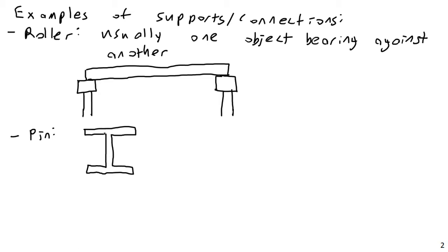So now what we do in steel design is we basically assume that the flanges here and here carry all of the moment and the web carries all of the shear. That's not a perfect approximation, but it is good enough for most design cases. So we treat the flanges as carrying all the moment and the web as carrying all of the shear.